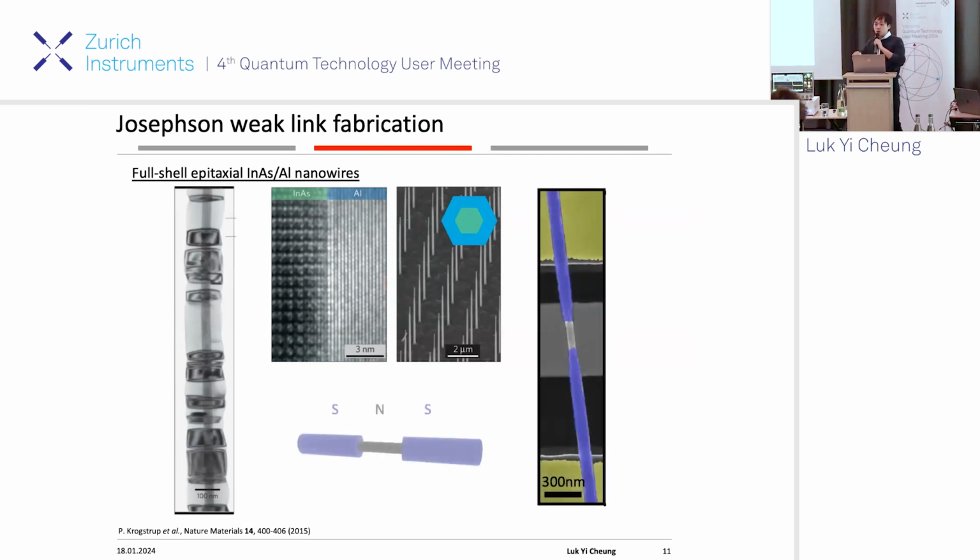In the lab, we make the chip, first a resonator chip, and then we suspend our nanowires on top of the resonator chip. And then we also etch away a small section of aluminum here to form the qubit. I want to emphasize again, the physical location of the qubit is really within this small 200 nanometer segment of indium arsenide. It's very different from the transmons, which are like 100 micrometers big. Great.